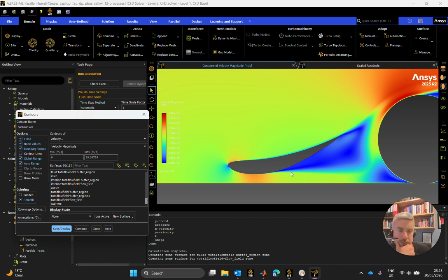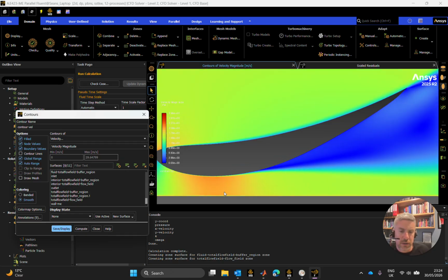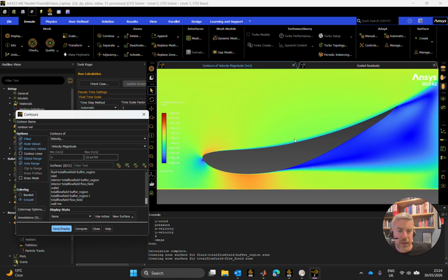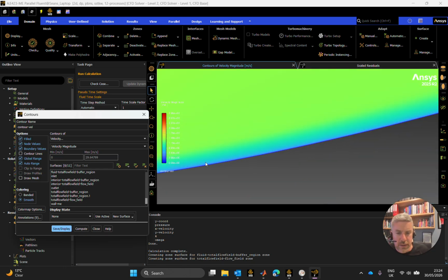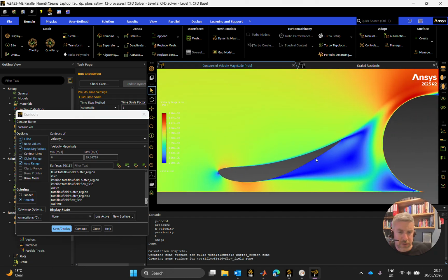Very big separation region, obviously, here to the back, where our boundary layer breaks away. We're losing too much energy off of the flow by the time we get to here. That acceleration has died off very quickly with this adverse pressure gradient obviously building here, which has detached the flow and hasn't been able to be reattached. We're at too low of energy there, where on the top surface here we can still see a very low pressure region, which should be giving us our very high velocity region there, which means we still are generating some downforce pressure off of the top, even though we have a big wake drag region here.